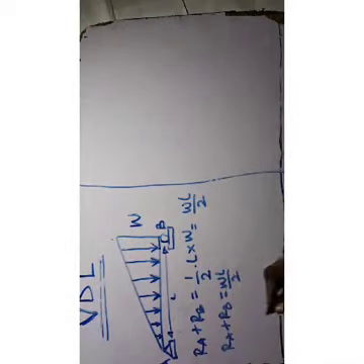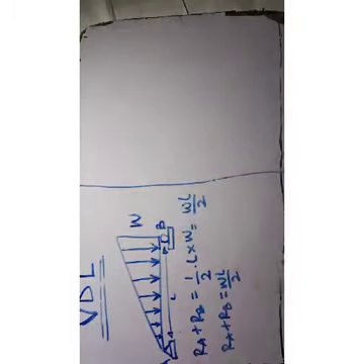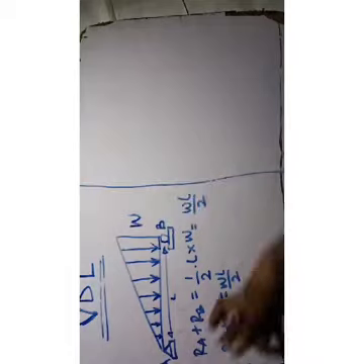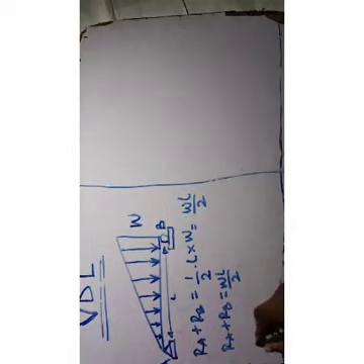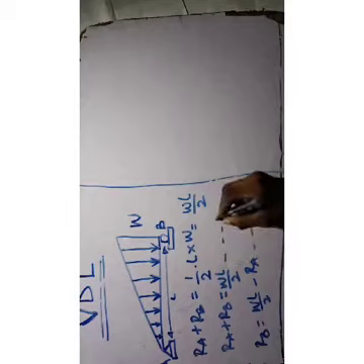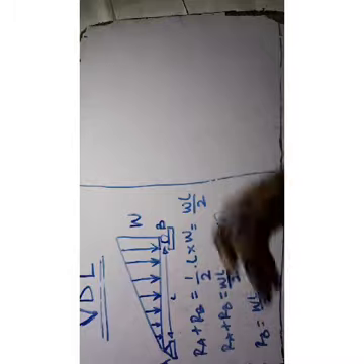It's very important. So I'll take my moment about point B for this concept. You can take your moment at point A anyway, but don't forget the 2/3 and 1/3 parts. So let's say I take my moment at point B here, and I'm going to have my RA with the direct here. From here we can say RB equals WL over 2 minus RA. This is equation 2, and the earlier one is equation 1. From this concept you can find the reaction at point B.